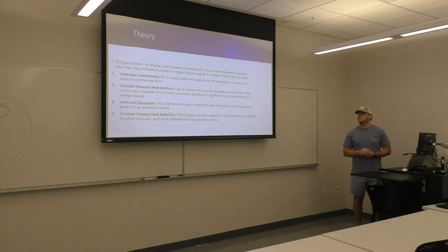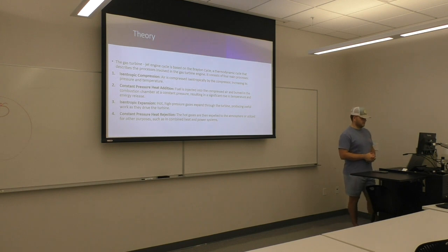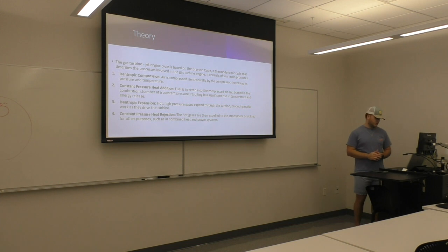Fuel is injected into the compressed air and burned in the combustion chamber at a constant pressure. You have the isentropic expansion. High pressure gas expands through the turbine, and then we have constant pressure heat rejection. The hot gases are expelled to the atmosphere.